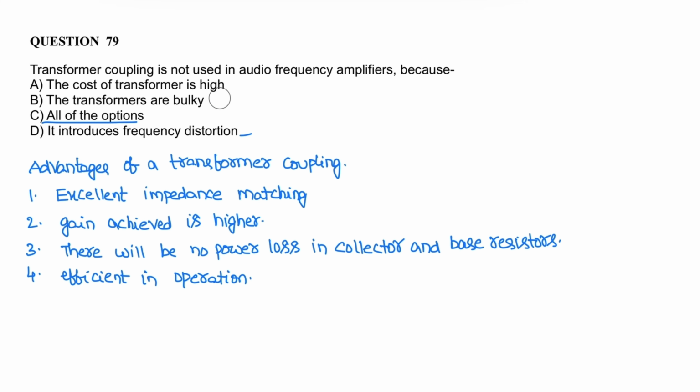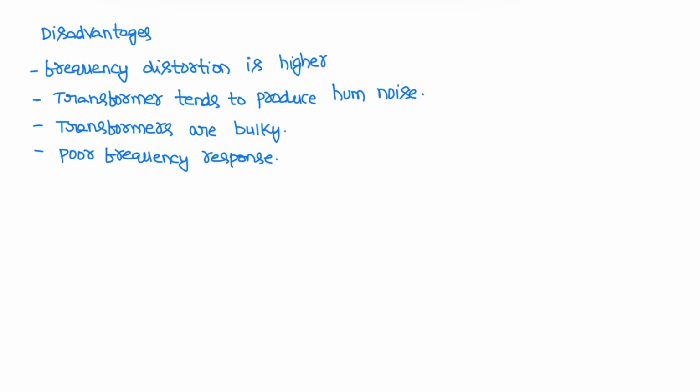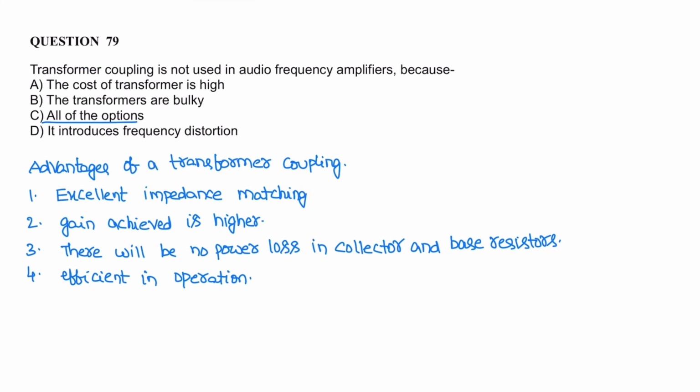Let us see disadvantages of this transformer coupling. Frequency distortion is higher, a major disadvantage. Transformer tends to produce hum noise. Transformers are bulky as well as costly, and poor frequency response. Because of all these, we are not using transformer coupling in audio frequency amplifiers.